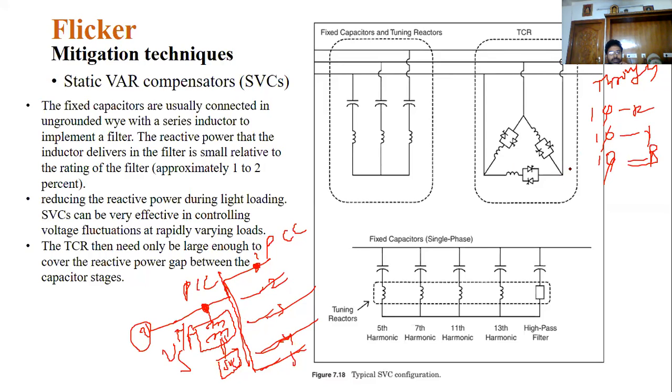We already discussed the advantage of this. Whenever you are connecting, you know on which phase the system will get the voltage regulation problem. Out of the three phases, perhaps only the R phase, or the Y phase, or the B phase is getting the voltage fluctuations. You are not assuming that all three phases get the fluctuation at a time. So by using three single-phase transformers, we connect this type of static var compensator.